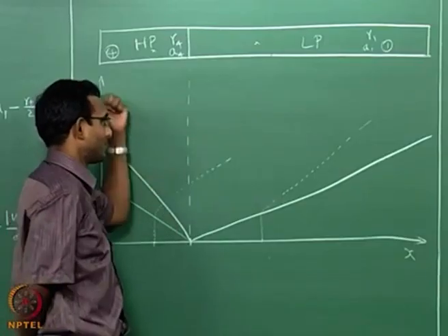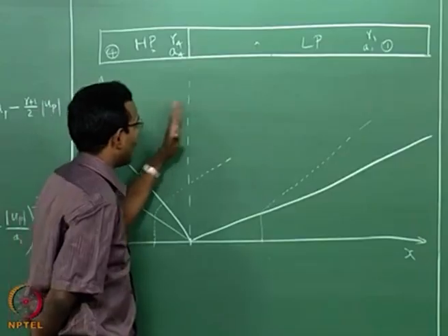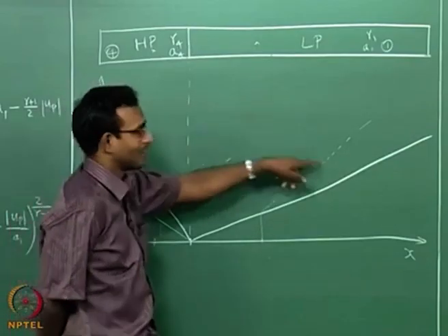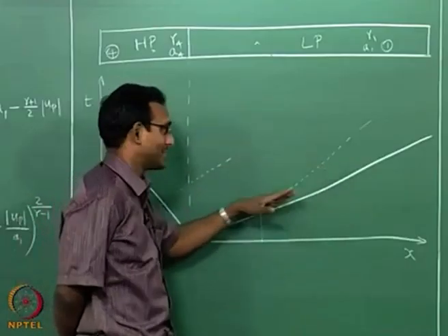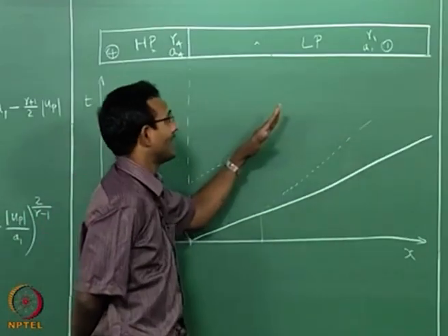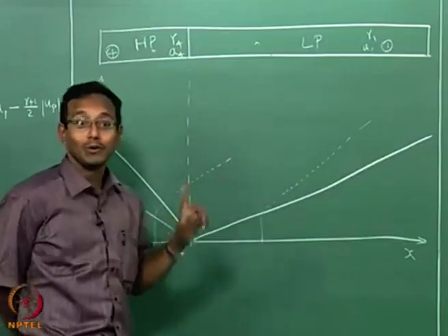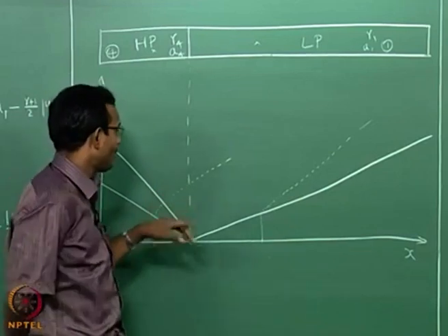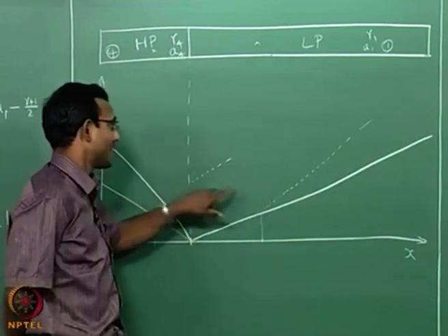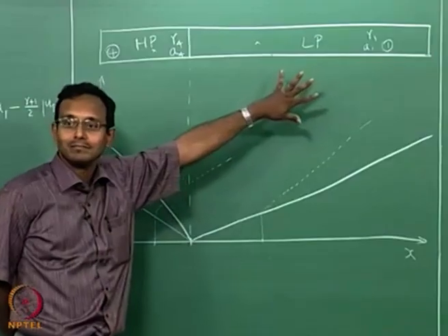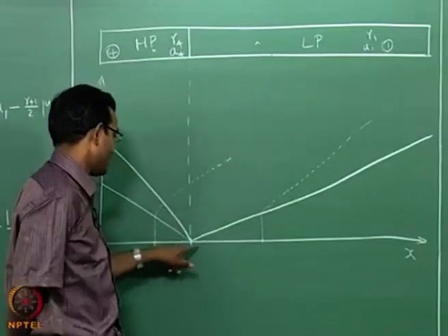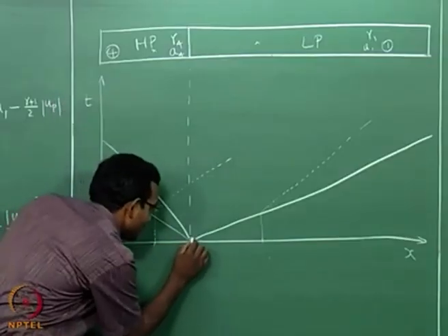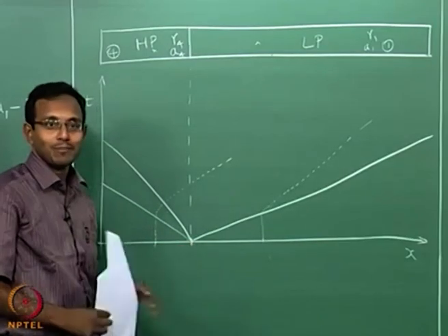Expansion fan from here going this way will tell the fluid to accelerate and fill that space, so the fluid will turn this way. Expansion fan going here will go and decrease the shock strength so that it does not go that far, but it will go a little more like this. So it will go to a point where it will finally have a nice equilibrium of these two velocities being exactly equal, that is these two lines are parallel. Till that time it is not a stable system, and all this happens in this small region itself, which I am not going to discuss too much.